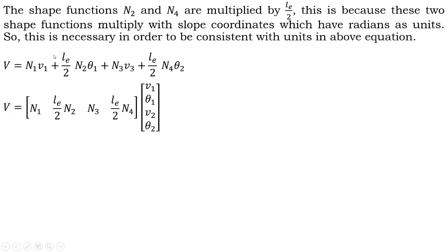Now this equation I'll represent in the form of a matrix, because FEM deals with matrices. So let us put that in matrix form. I'll take all these displacements outside. Then it becomes n1, le by 2 n2, n3, and le by 2 n4, multiplied by v1, theta 1, v2, theta 2. When I multiply this matrix and open it, I'll get the same equation.